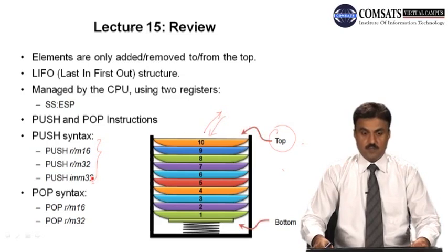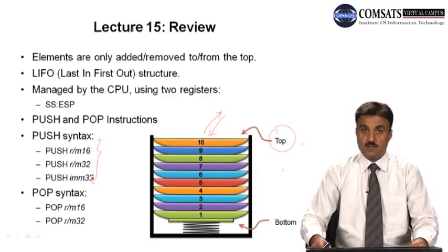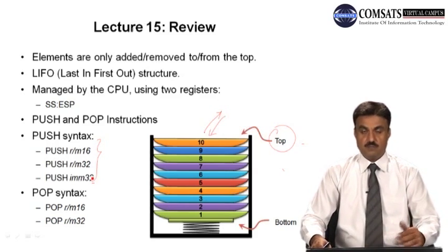On the other hand, the pop instruction first reads the value from the location pointed out by the stack pointer. The combination of stack pointer and stack segment is used, and in the flat memory architecture only the stack pointer, and then it is adjusted. So the operation is totally reverse.